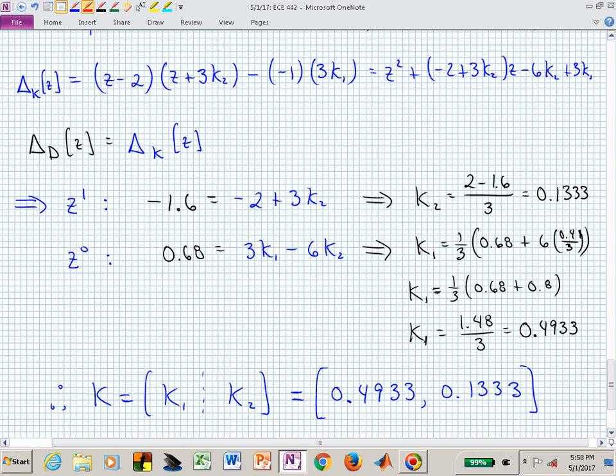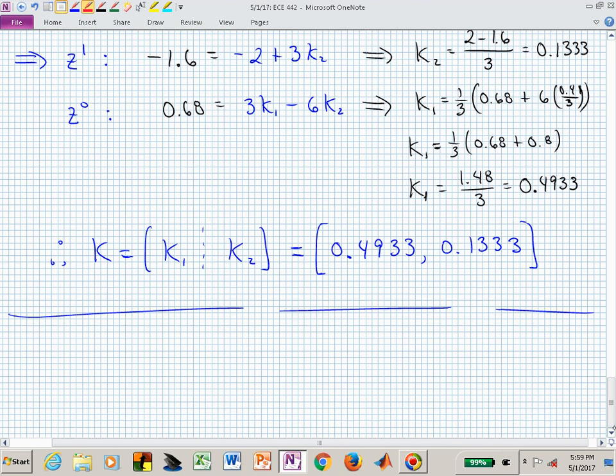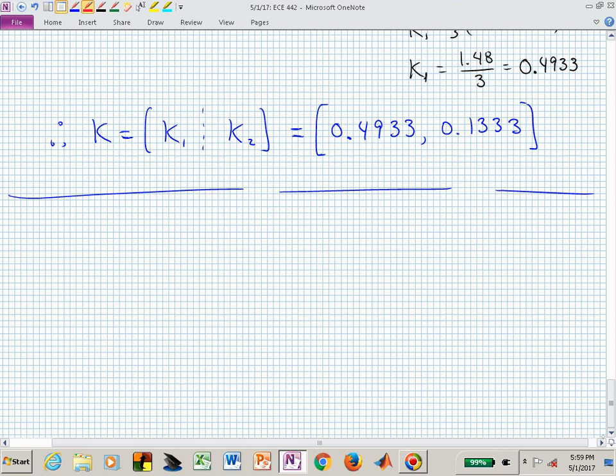And if K is 1 by 2, multiplying a 2 by 1, that will give you a scalar 1 by 1. So one of the tips that you get for attending today's lecture is make sure you get the dimensions of K right. If you have a single input, K needs to be short and wide.